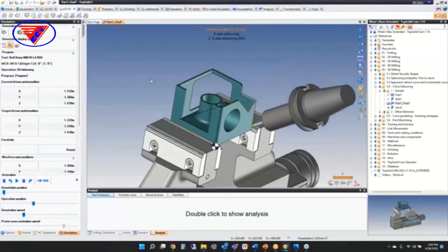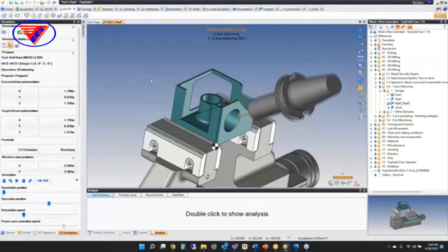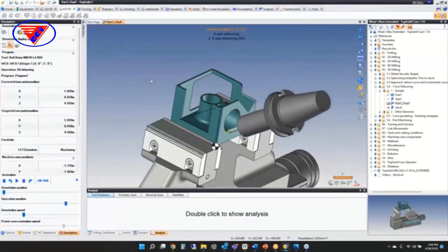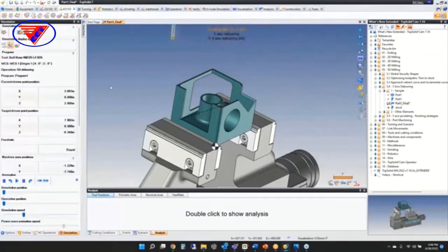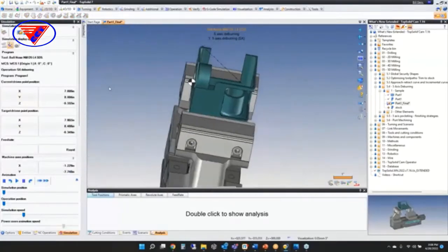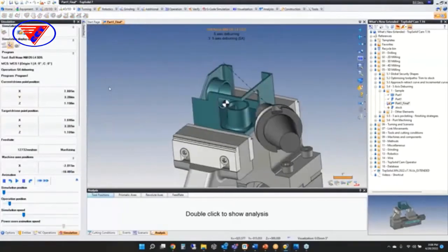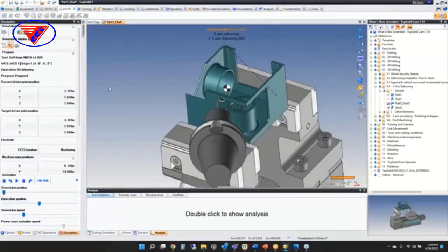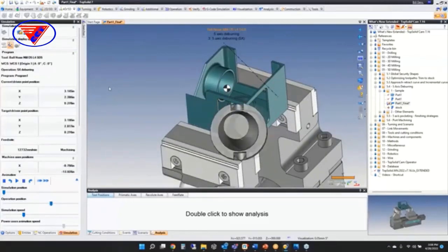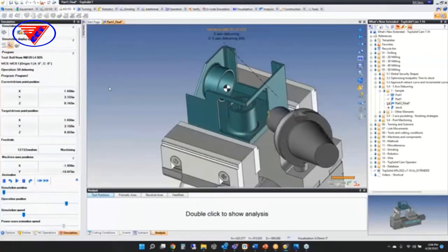So I can specify a specific angle, come in here, and break some edges. Something cooler that can happen there too. This one now is going in full 5-axis continuous to do that inside profile while I'm maintaining an angular, or a range between angles that it can swing.